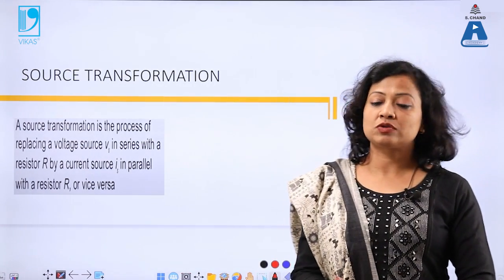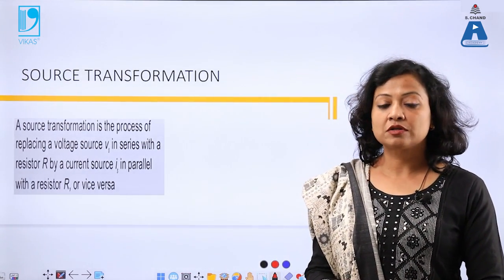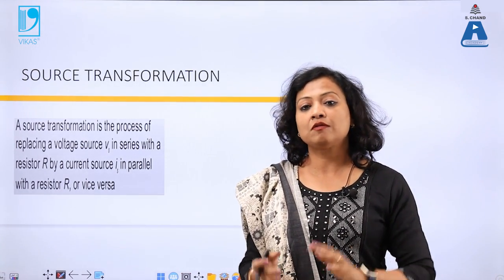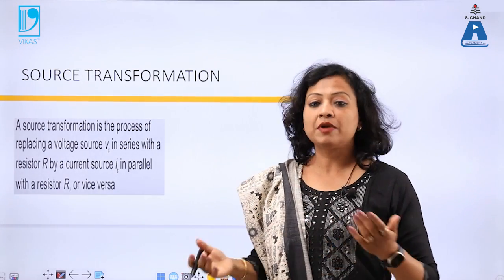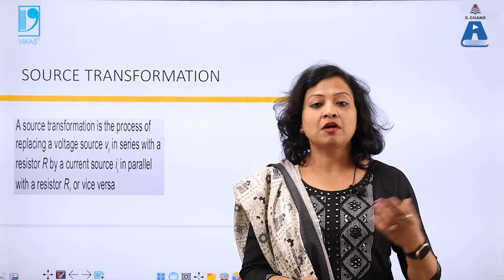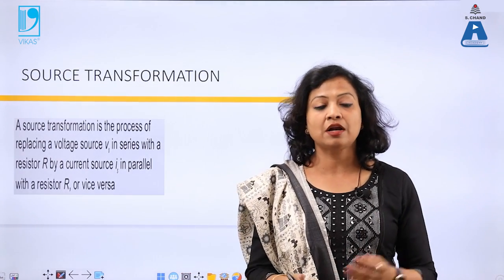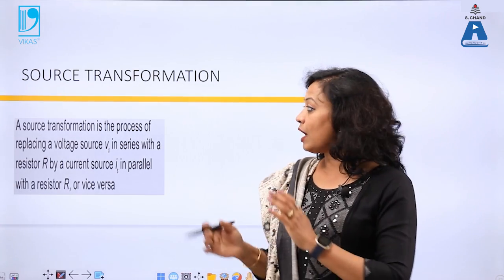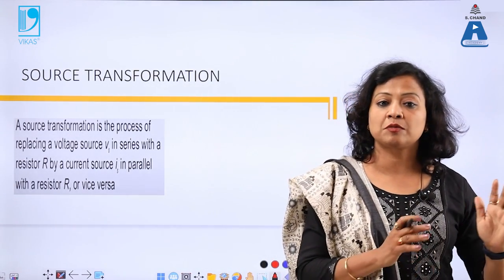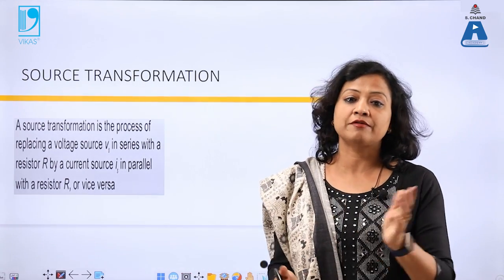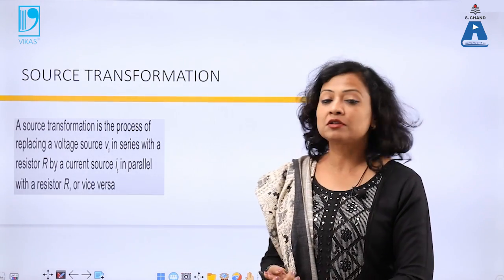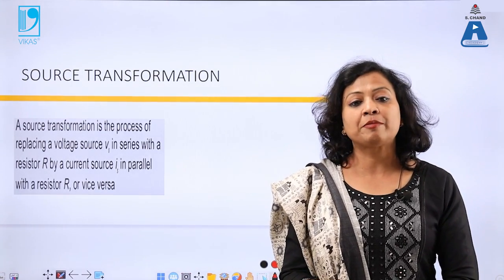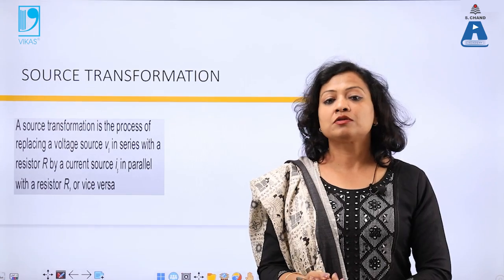Now, why do I need source transformation? I need source transformation to make my complicated circuit a simpler one. To solve a complicated circuit, sometimes there are a number of sources, like voltage or current sources, and I cannot add my voltage source with a current source or simplify my circuit. So, I transform one form of source, suppose a voltage source, into a current source and vice versa. By transforming these sources, I can easily get the algebraic sum of all the sources